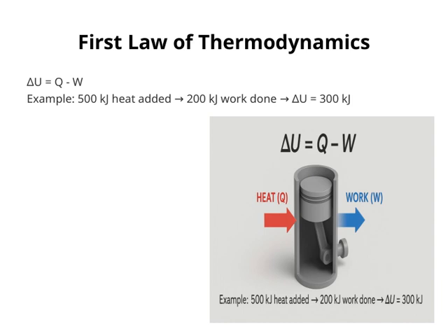of that energy. For example, suppose we add 500 kilojoules of heat to a system. If, during that process, the system does 200 kilojoules of work, the net change in internal energy, ΔU, would be 300 kilojoules. This example highlights how heat and work directly influence the energy content of a system, which is a crucial concept in thermodynamics. Connecting this to the overall theme, understanding this relationship helps us analyze real-world energy systems, whether in engines, refrigerators, or power plants. It's all about tracking how energy flows and transforms within systems.